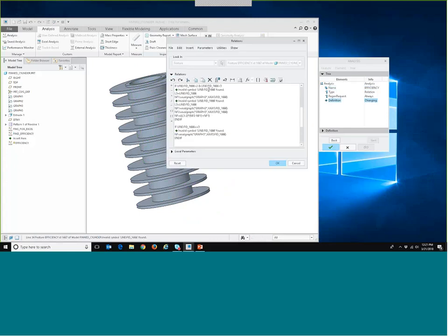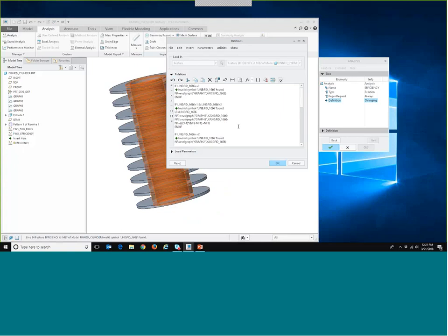And again, we had this just as a dummy variable initially because we didn't know the feature ID of the find efficiency analysis that we were doing, so we just left those in as 1666. So what we'll do is replace that now with find_efficiency. Within this relation, we can find and replace that value, and we will replace the 1666 with find_efficiency, replace all of them, and verify the relations.